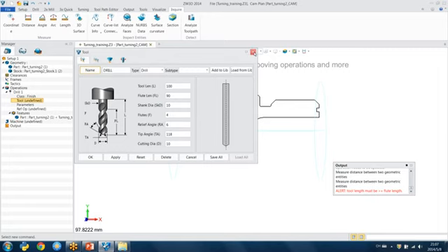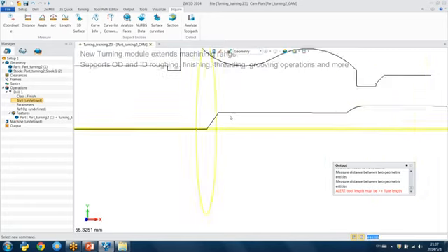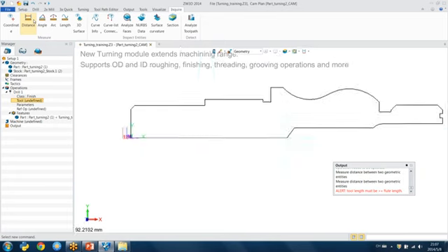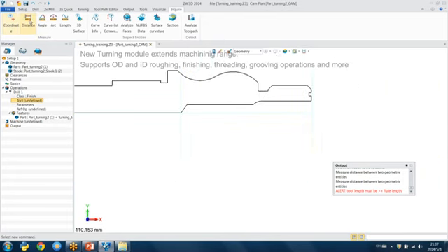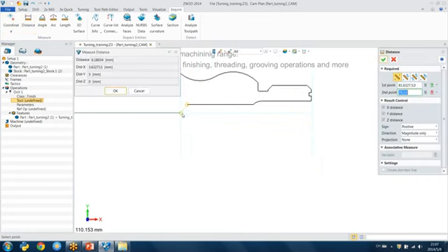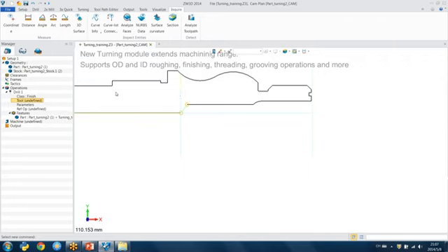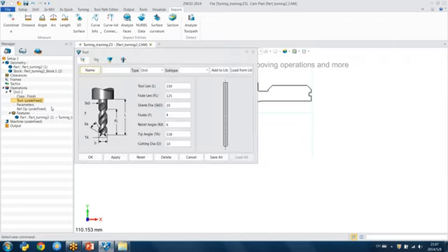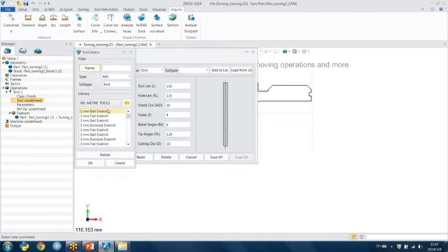Oh, you also need to know the size of the hole. So the same with the distance, check. Y distance is 5, so the diameter is 10. So okay, select. You can also load the tool, load the drill from the library.